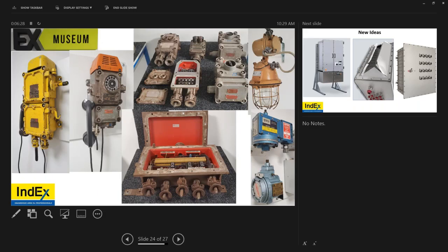If EXD equipment is being modified to include additional terminals, okay, if you want additional terminals and it's approved by the certificate and IOMs, go for it. Same size, whatever, you follow their tables. It's usually in the annex or in the conditions of use. Now, if you're doing something different, no, don't do that. It's unsafe. Call the manufacturer, ask them for their solution.